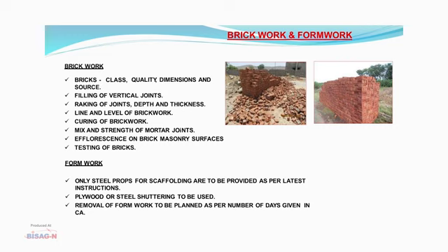For the formwork used for supporting the various RCC activities, it has to be ensured that only steel props are used for scaffolding, and wooden props are to be avoided at all costs as per the latest instructions promulgated from the ENC's branch. Also, steel shuttering should preferably be used at various inaccessible places or uneven surfaces where the dimensions are not as per the standard dimensions. Plywood can be used. Removal of the formwork has to be planned well in advance so that a fair finish of the concrete is obtained.